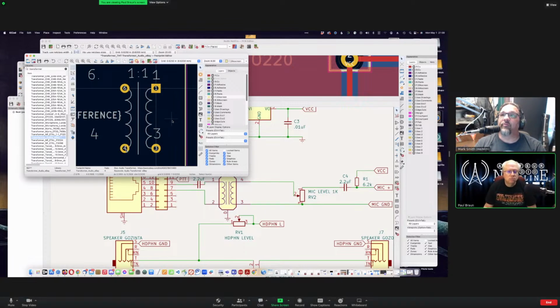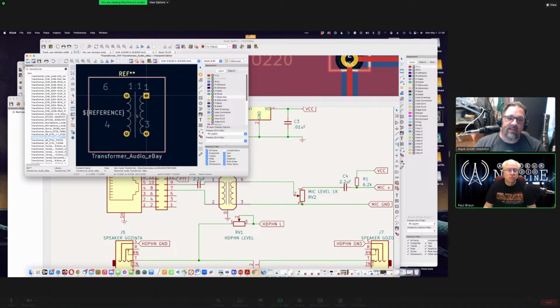Okay, hover over pin 4. Minus 0.2 and 0.4. So that's the correct spacing. Oh, so the way it is. Yeah, just the way it is right now. Now, the outside bounding box of the transformer... We need to get rid of this too, right? The 6 and the 4. Yeah. Those are fab. Just delete all of that. I don't think it's going to show up. All of that light gray stuff, just delete it. It's not going to show up anywhere.